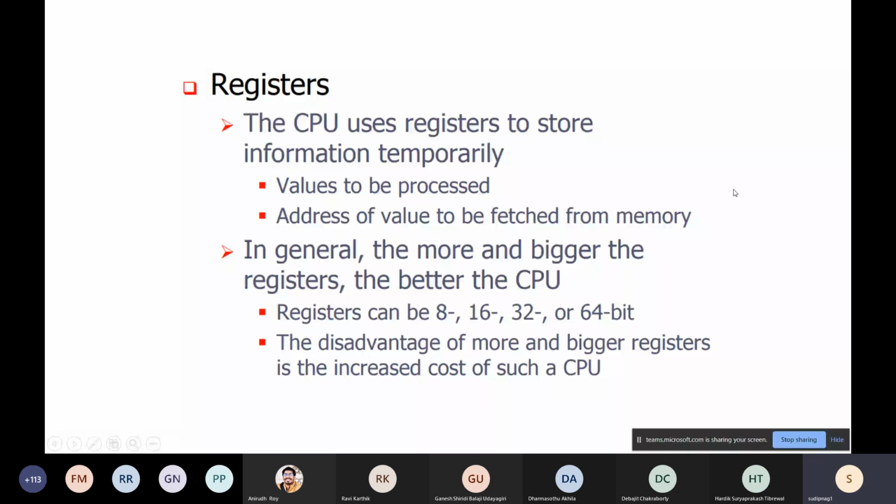For a RISC microcontroller that came up after the CISC variant, in fact, AVR came up to solve certain major drawbacks of 8051. In 8051, pipelining was not present. So in AVR, that's why they introduced pipelining. But AVR's pipelining strategy is very primitive these days, I'll say, because ARM and other processors are really outperforming and they're much more modern even in the pipeline design.